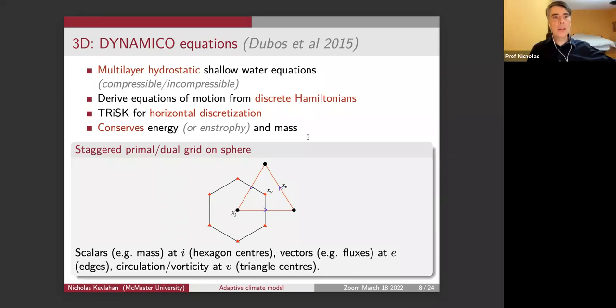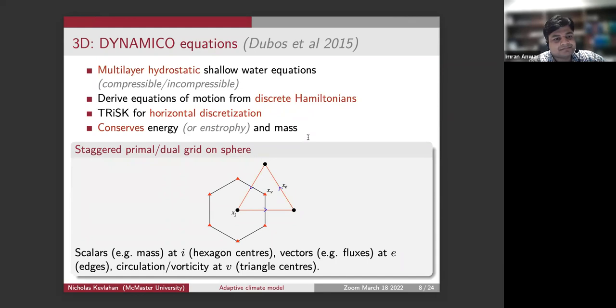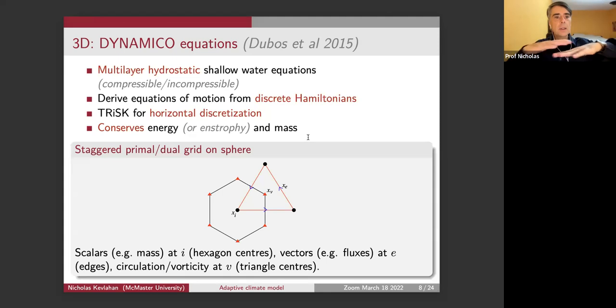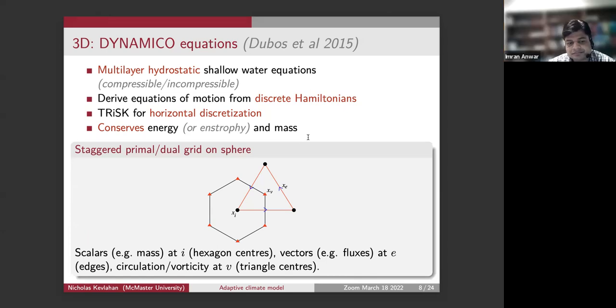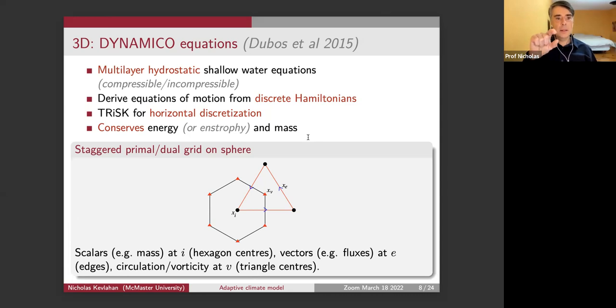So shallow water, it's what I said very early on at the beginning. Shallow water means that you imagine you have the ocean and you average in the vertical direction. So what you'll get is a two-dimensional equation, but where the variables are the two components of velocity and the height of the water column. That's a good approximation where you have very long waves and shallow depth. The waves are long, the wavelength is long compared with the depth of the layer.